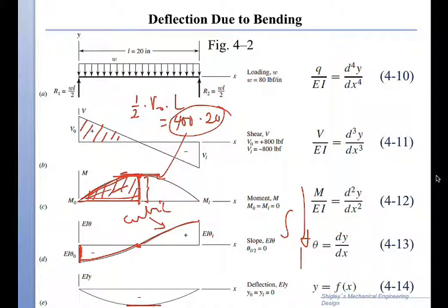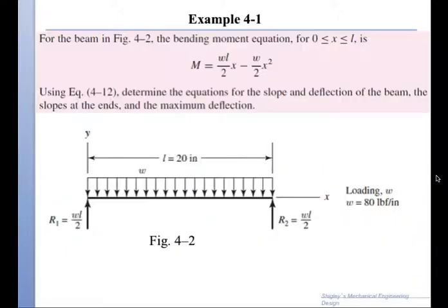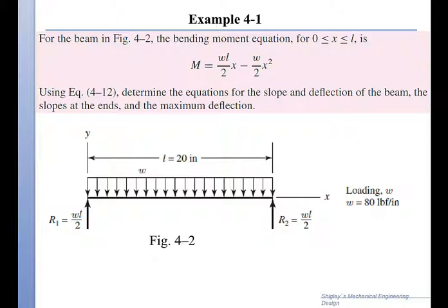And then one more integration, we get the deflection curve EI y, and the deflection curve, as you can see here, will be a function of x. This is a quartic value. So this is all that is involved in finding the deflection graphically. As you can see, it depends a little bit on common sense and experience.